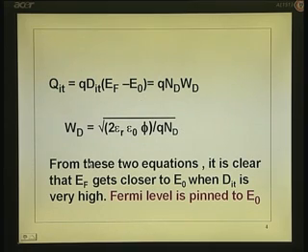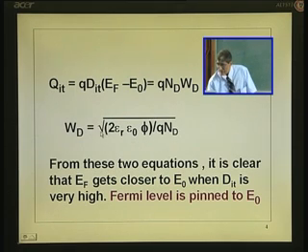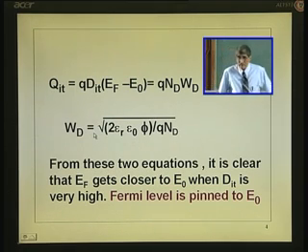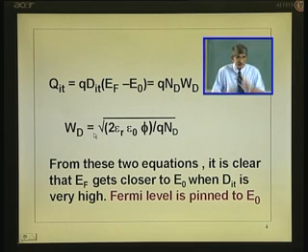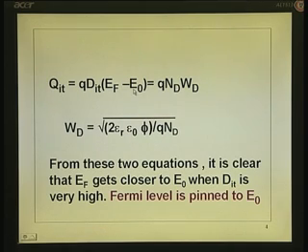What is W_d? W_d is the depletion layer width, and that is decided by how much the potential drop is. The usual law is phi equals Q N_d W squared divided by twice epsilon epsilon_0, a very well known formula for the depletion approximation. Now, you can see the whole thing has hit an equilibrium, so that the location of the Fermi level is such that E_f minus E_0 is equal to that quantity, and that quantity is decided by the potential.